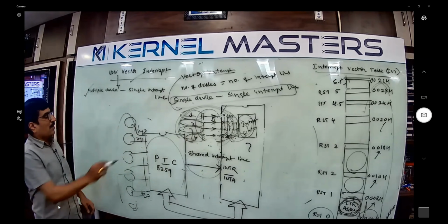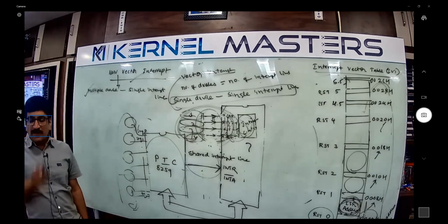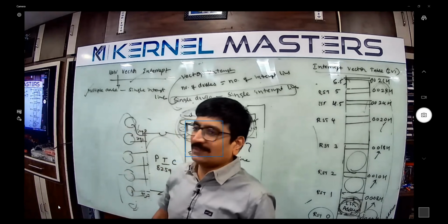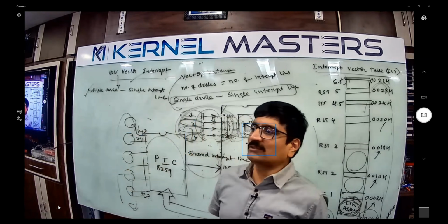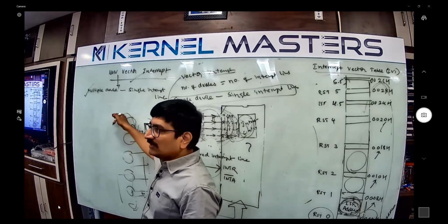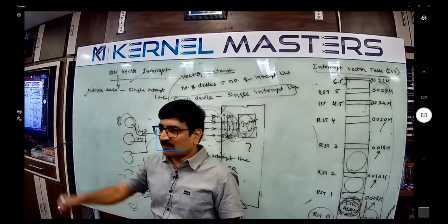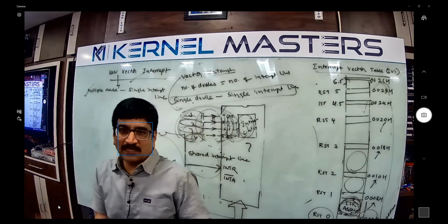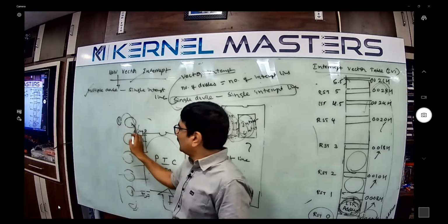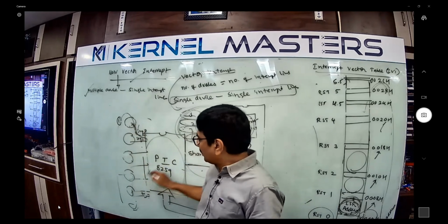Now I'm going to explain clearly how a non-vector interrupt works. If somebody asks how an interrupt works, explain these same steps. The first step, the starting step, is the device raising an interrupt, like my phone ringing, or a keypad being pressed. That is triggering, either rising edge or falling edge. So first, the device raises the interrupt, and the interrupt comes to the 8259.